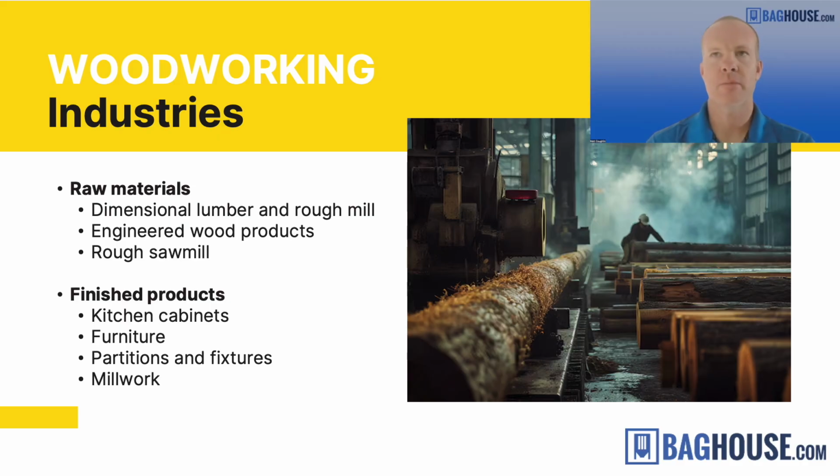The dust collection system approach varies a little bit depending on the type of processes in the shop, but overall the approach is similar. We may adjust some things based on the materials, if we're working with hardwoods versus softwoods or engineered lumber. If we're talking about collecting heavy chips versus very fine light dust, that might inform our decision on how we size the dust collection system, the ductwork, and maybe some filter media decisions, but overall the approach is pretty much the same.